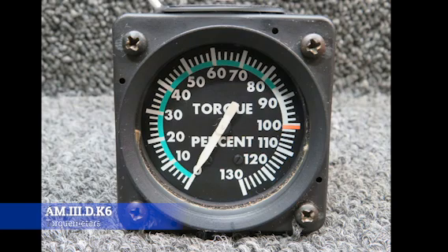Not too different than, say, your altimeter or anything else like that, except instead of atmospheric pressures, it's using engine oil pressure. This gear moves against the piston that controls the opening valve, which controls the oil pressure flow. The action makes the oil pressure proportional to the torque being applied to the propeller shaft. So generally, they've packed the math into that gear ratio, which is pretty intelligent.